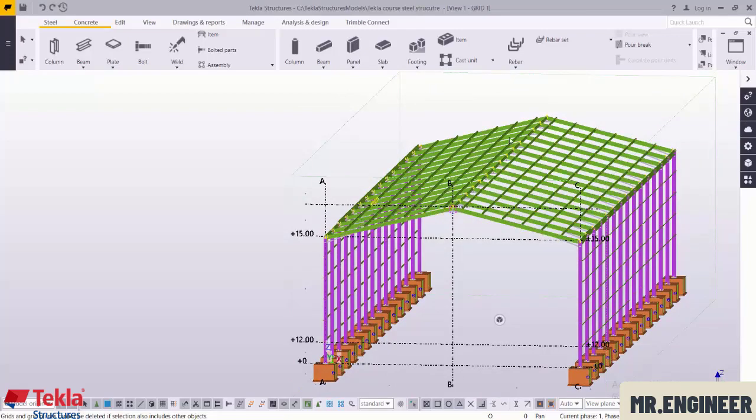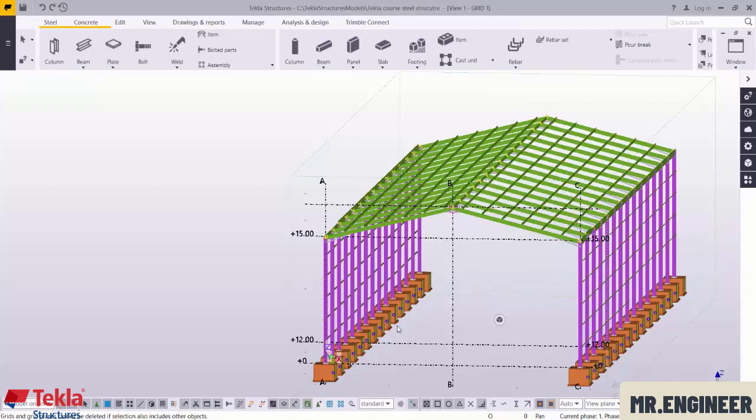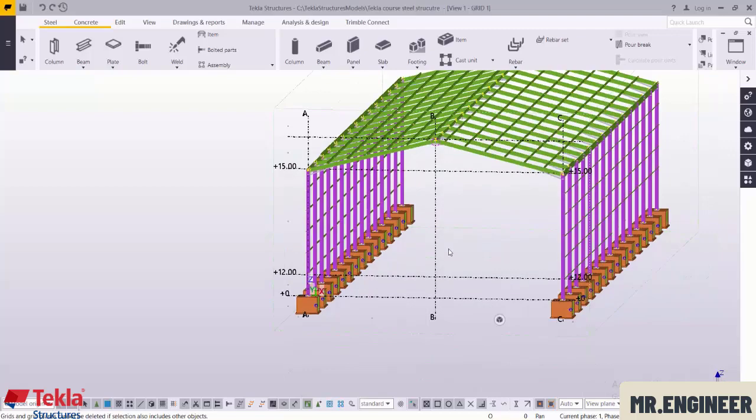And we copied the connection and used the work plane option to create the XY plane, to move the XY plane to here. Then we removed the XY plane from here and put the origin 0 0 here. Okay, now we want to model the columns that resist against wind load.